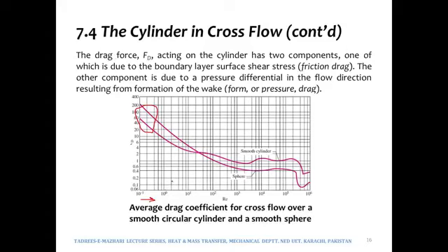Right, so there would not be any flow separation in this regime, as we had seen in one of the previous slides, that if Reynolds number is less than 1, then the flow will remain stuck to the cylinder for the first half, and even on the second half of the cylinder as well.